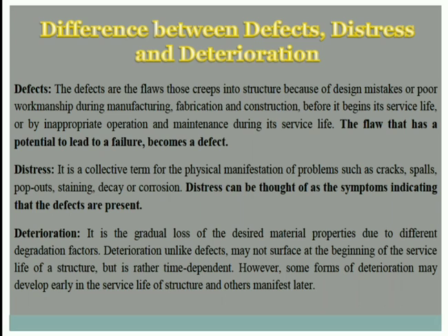Then deterioration, it is a gradual loss of material properties due to different factors. Deterioration, unlike defect, may not surface at the beginning of the service life, but is rather time dependent. However, some form of deterioration may develop early in the service life of the structure. So deterioration is something which is happening gradually. The material gets deteriorated, so the ability of the structural element to hold the load becomes lower and lower.